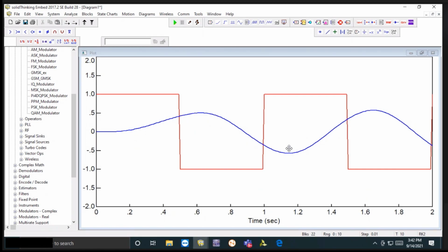Here some time shifting is there. As I already told you, time shifting and amplitude variation are always allowed, because it depends on the amplitude we have taken for the master signal and the carrier signal. First thing. Second thing, we have taken the master signal directly, and the demodulated signal is coming after modulation and demodulation. So the processing times for both of them are different. So this thing is always allowed.